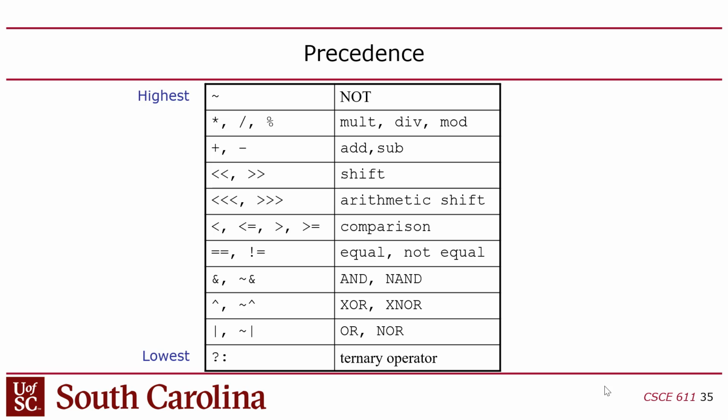Oh, by the way, we do use a multiply in the ALU we use for this class, strangely, but it just seems to work out for us, because for this class we're running at a low clock rate and we have plenty of FPGA resources. So we do actually use it in this class to synthesize. I did try divide though, and that never worked because it ate up the whole FPGA. I tried to create a single cycle divide in the ALU, and it was too expensive. Something I hope to fix one day.